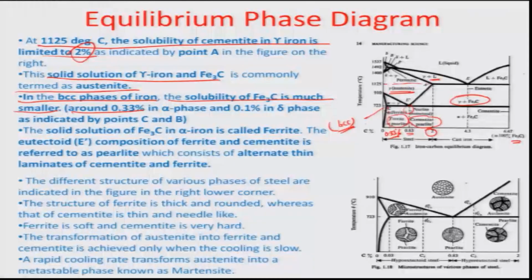So, if I look at the structures here, this is how the pearlite would look. It is one uniform homogeneity, the mixture of ferrite and cementite. On the other hand, look at how the mixture of ferrite and pearlite can be. There are some additional white marks here, although these are not the actual structures, it is just a cartoon indicative of what is going on.